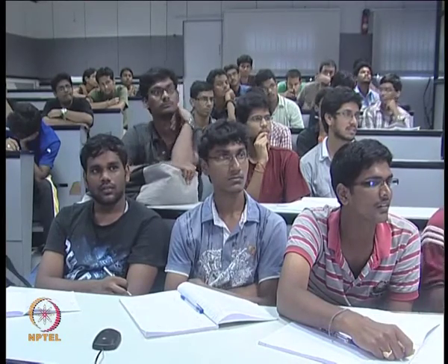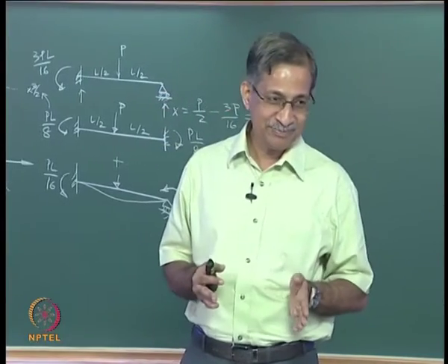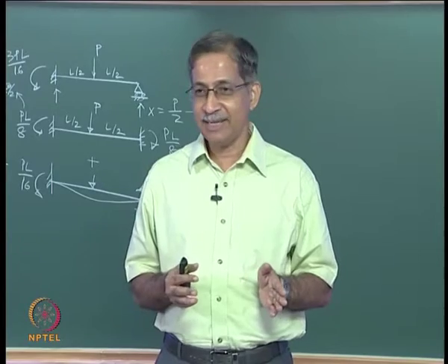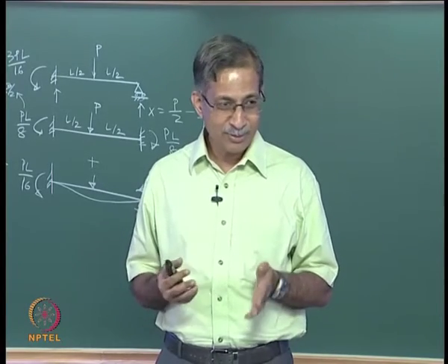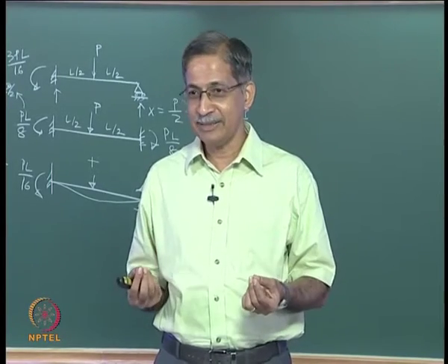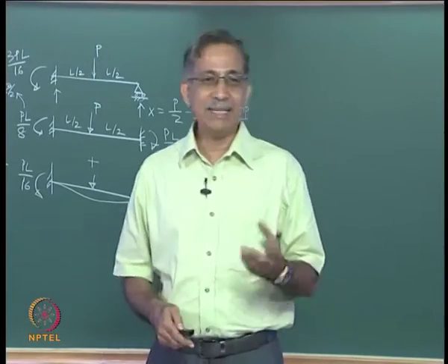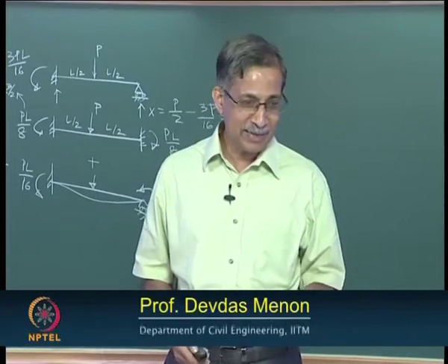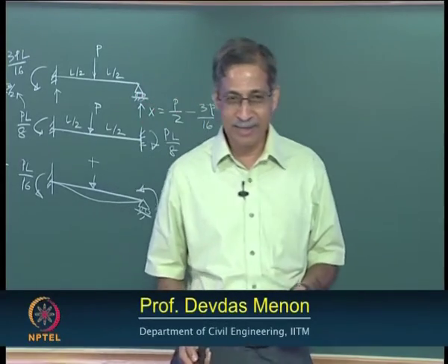CD and EF are supporting because they are stiffer. See, the stiffer fellows will support the not so stiff beam. Can't you feel it? Ultimately the deflections are the same. So it does not matter. Let us say you made a mistake, it will show up with a negative sign in your reaction, but it is good to get it intuitively right straight.